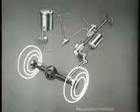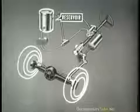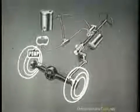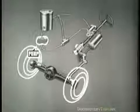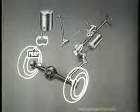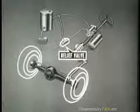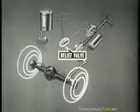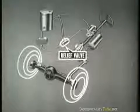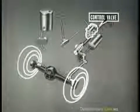Now let us review the operation of the hydraulic steering system. The reservoir supplies fluid. The pump, driven by the engine, delivers the fluid under pressure through the relief valve to the control valve. The relief valve provides an escape for excess pressure back to the reservoir. The control valve directs fluid to the power cylinder.